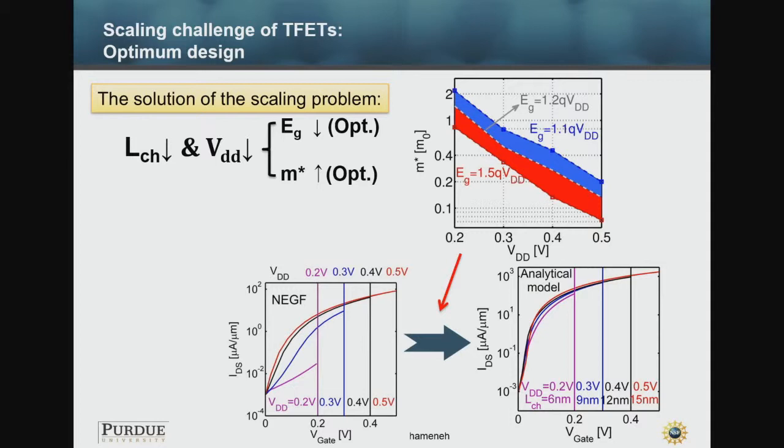All right. Okay, very quick question then. Go ahead. I had a question about the 2-gate design. How close are those 2 gates together, and how much voltage are you expecting to put across there? Essentially, I'm asking, wouldn't you expect your gates to leak to each other very heavily?